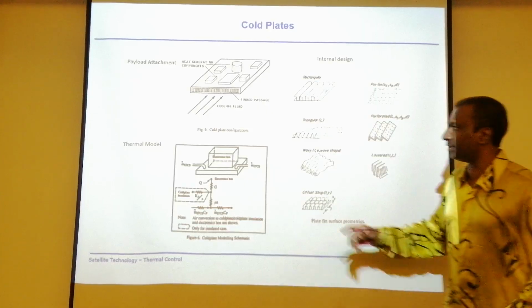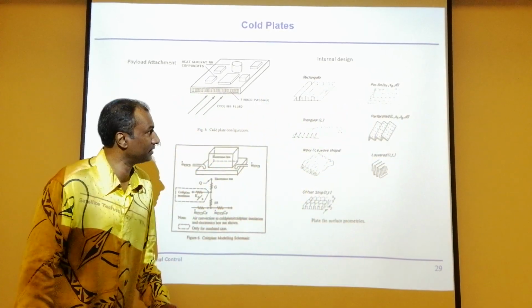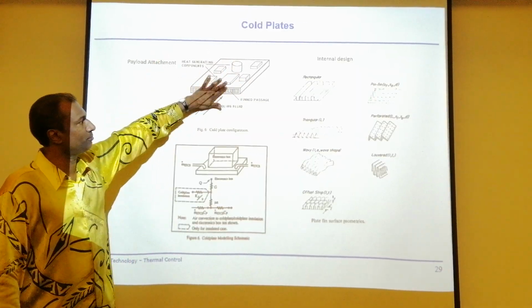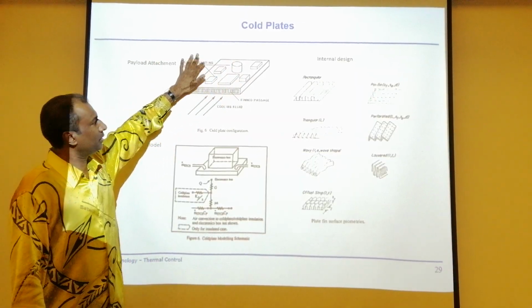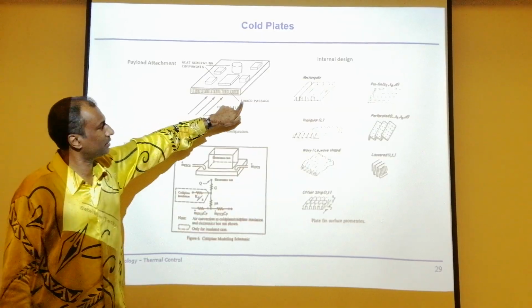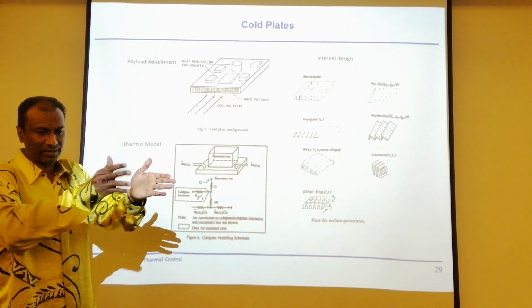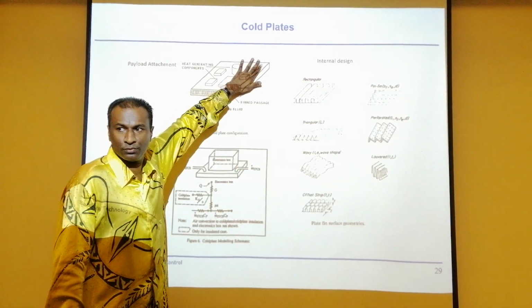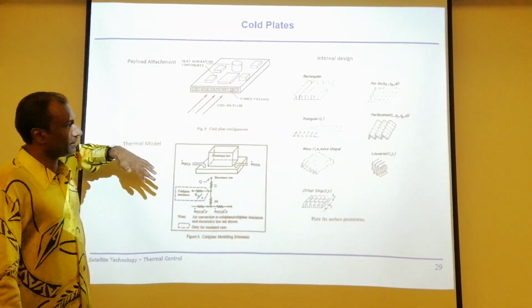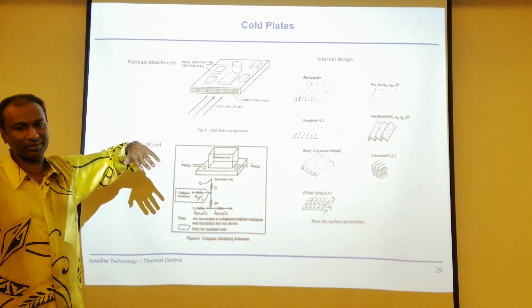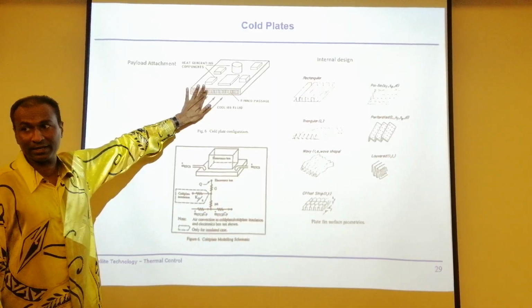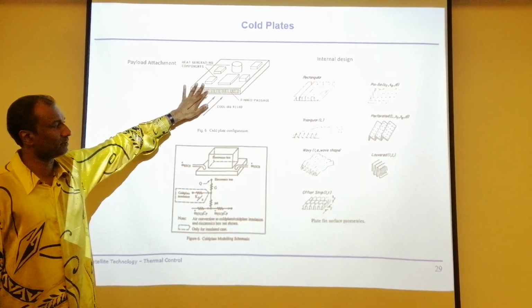Okay, this is cold plate, as you can see, single phase. All your equipment is on top, battery, your onboard computer. Then you have a thin passage, that means to increase the surface area. Fluid flow comes back, then the heat is actually ejected. You don't have this in a satellite, but you will have it in a huge spacecraft.